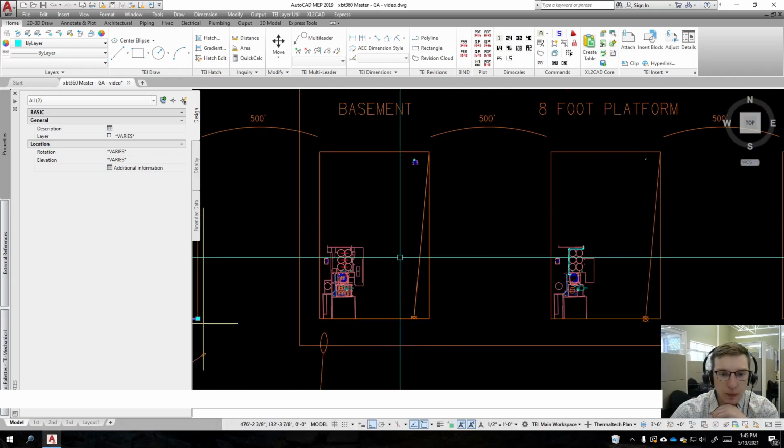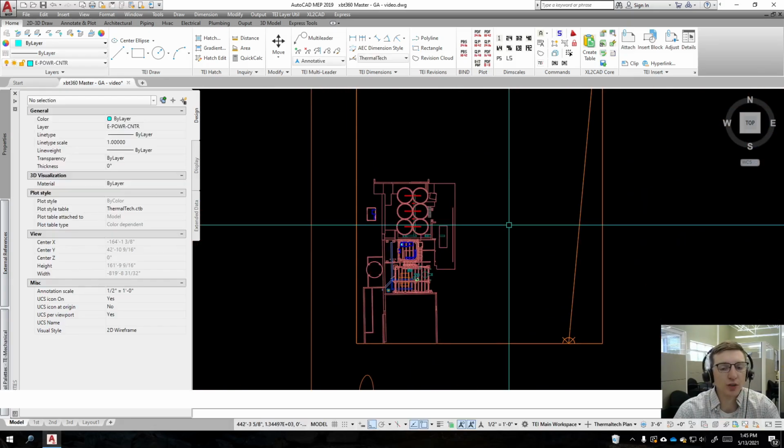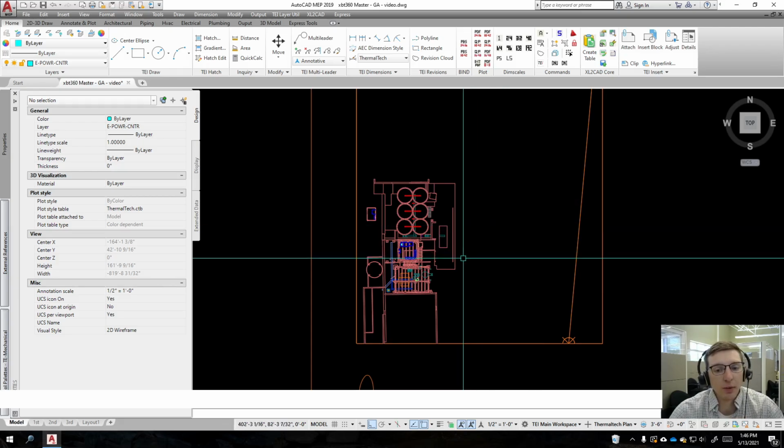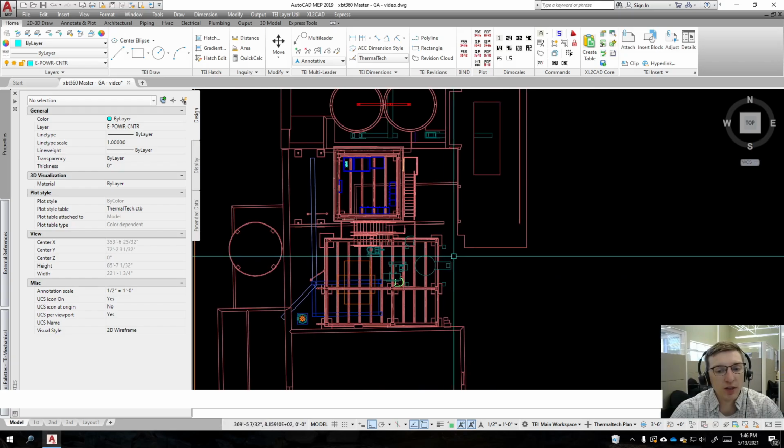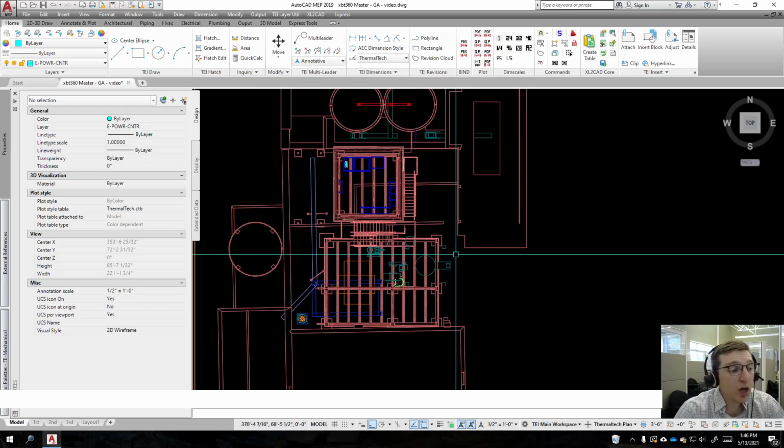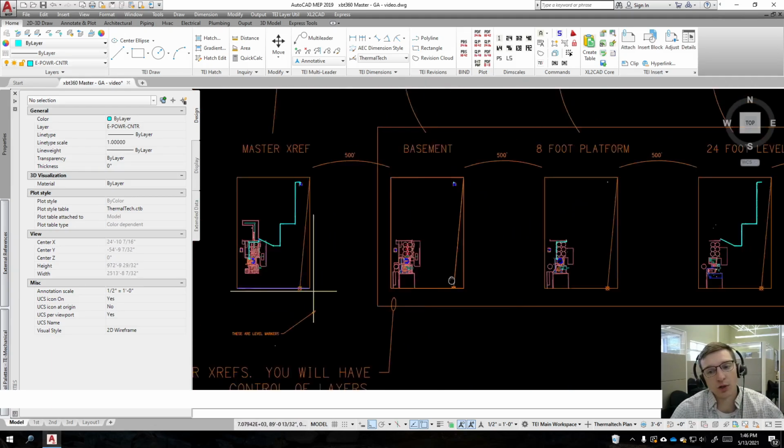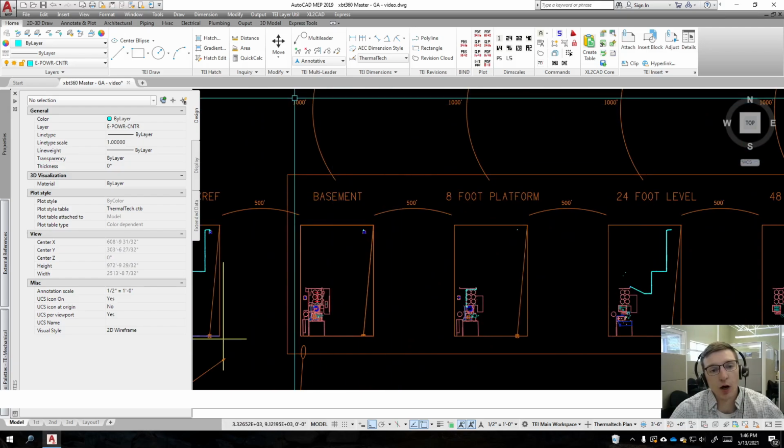Copy down 1,000 feet. And then what I actually do is I need to be able to freeze my layers and adjust my layers, unfortunately, right? So I'm probably going to need to be able to show, my electrical discipline is going to need to be able to target my mechanical new equipment layer, and maybe my electrical drawings want those to be on a color that doesn't plot as dark. So if I need to have control over my layers, the second step that we're going to talk about is going to help you do that.